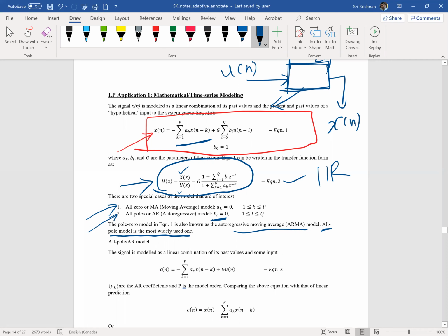So the all-pole model is very widely used in pretty much all biomedical signal applications. Whether you take vibration signals, EMG signals, speech signals, or for that matter ECG, phonocardiogram, even EEG, it's been shown that the all-pole model will do the job that's needed. We don't have to even go to the level of the ARMA model. The ARMA model is ultimate, it does cover both poles and zeros, but it's been shown that poles are good enough in many biomedical modeling applications.